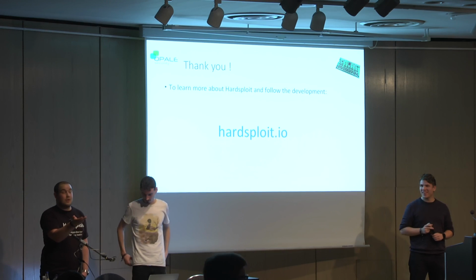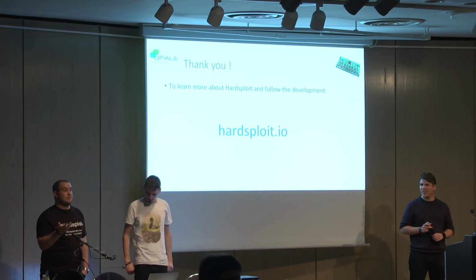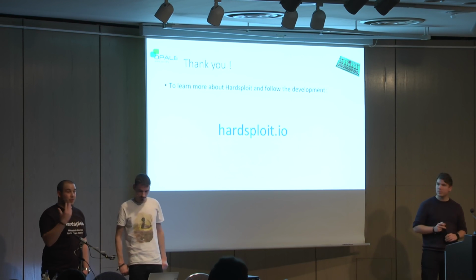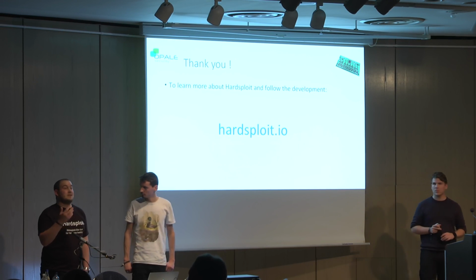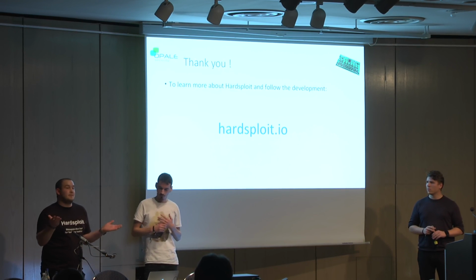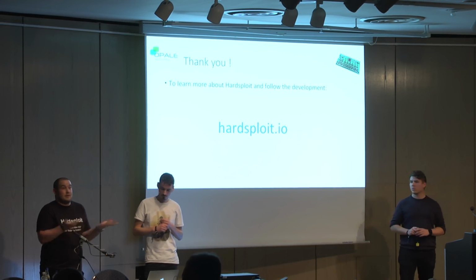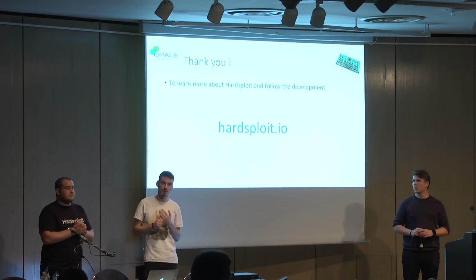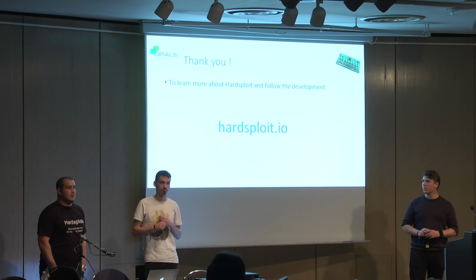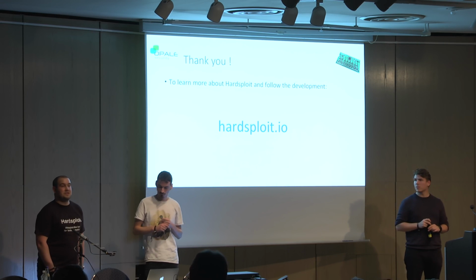Not exactly. You have a problem with internal memory of Cyclone 2. So it's complicated to answer your question, because the goal of Hardsploit is to create a versatile framework. And of course, the limit is only 7 nanosecond latency, because we work at 150 megahertz for the bus we want today. We are not limited by the FPGA. So just this limitation, just 7 nanoseconds, yes.